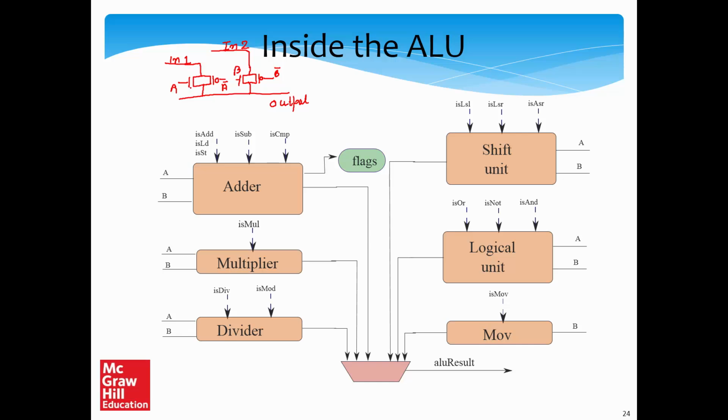All that we need to ensure is that A and B are not on simultaneously, and that can be ensured by the control unit. Pretty much, don't make A and B on simultaneously. Assume this transmission gate A is on, in the sense the switch is closed, then input 1 is the same as the output. If B is off, then input 2 is kept floating, so it is absolutely disconnected from the output. You can think of it as a switch that is not connected.